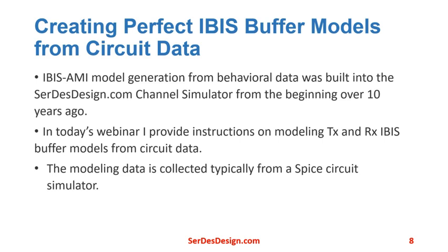Creating perfect IBIS-AMI models from circuit data. IBIS-AMI model generation from behavioral data was built into the SerDesDesign.com channel simulator from the beginning. I have used this process over the past 10-plus years, providing custom IBIS-AMI models to over 40 companies based on circuit data they provided me. In today's webinar, I provide instructions on modeling transmit and receive IBIS buffer models from circuit data. The modeling data is collected typically from a SPICE circuit simulator.